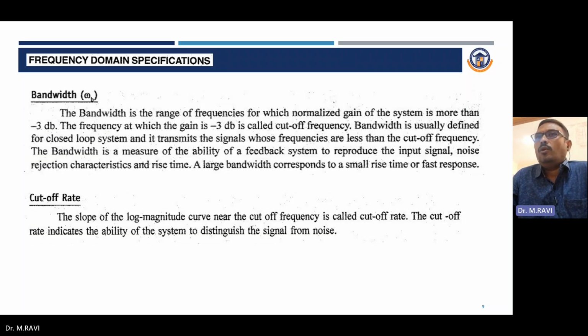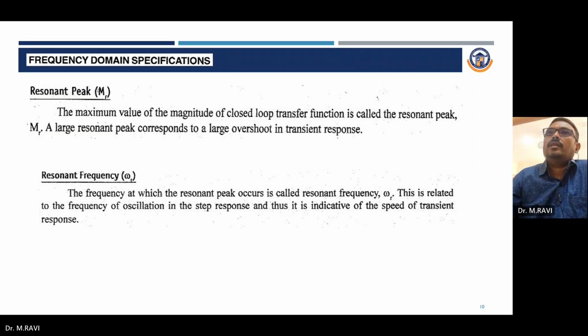Cutoff rate. The slope of the log magnitude curve near the cutoff frequency is called the cutoff rate. The cutoff rate indicates the ability of the system to distinguish the signal from the noise.